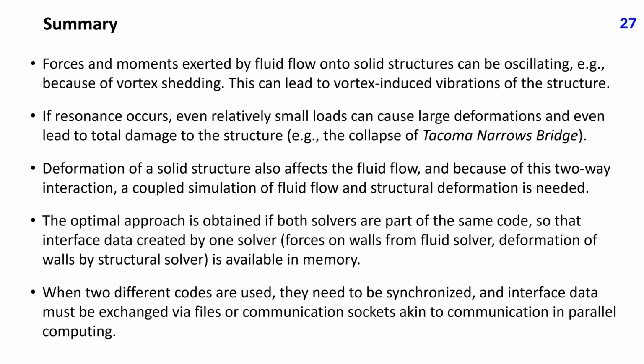Deformation of a solid structure also affects the fluid flow, and because of this two-way interaction, a coupled simulation of fluid flow and structural deformation is needed. The optimal approach is obtained if both solvers are part of the same code, so that interface data created by one solver, forces on walls from fluid solver, deformation of walls by structural solver, is available in memory. When two different codes are used, they need to be synchronized, and interface data must be exchanged via files or communication sockets, akin to communication in parallel computing.